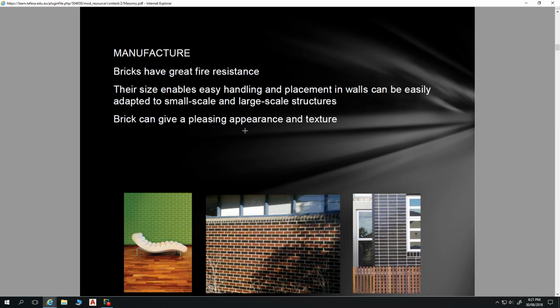These ones were about 20 millimeters, and the foam packing in the control joints was like this because the bricklayers had laid those concrete bricks and they had continued to shrink, just ever so slightly. So we're only talking a shrinkage of about 10 millimeters over 6 meters length, but that's enough to cause quite a visual problem in the building.